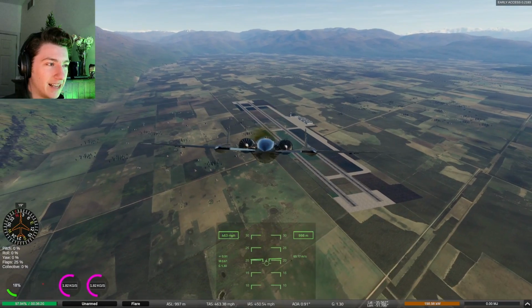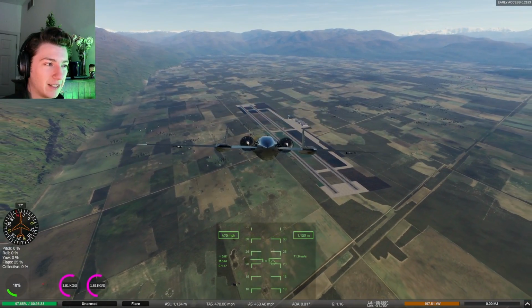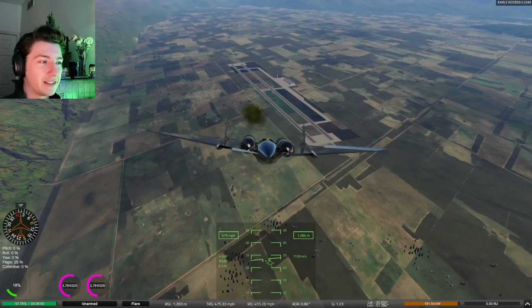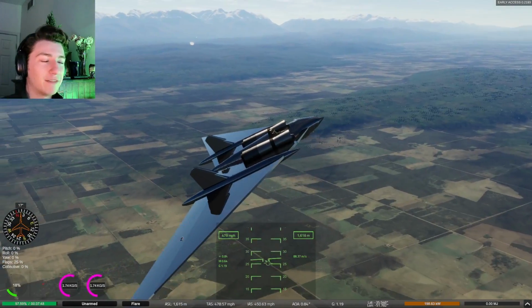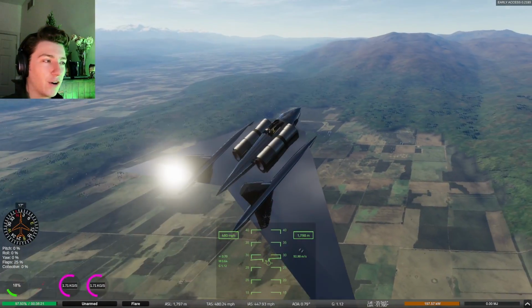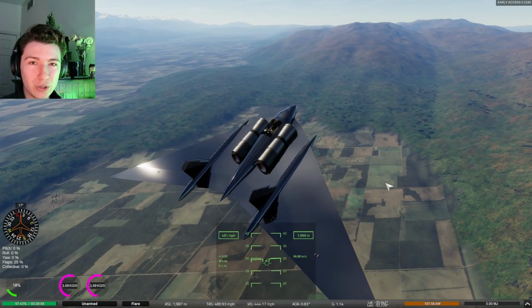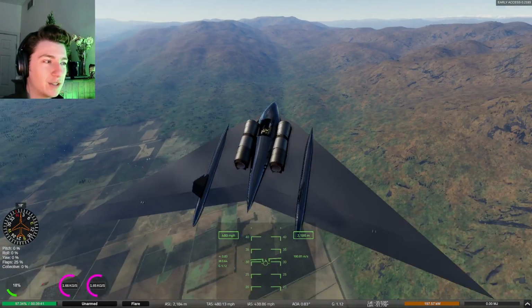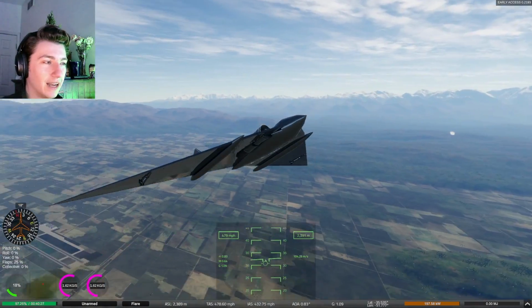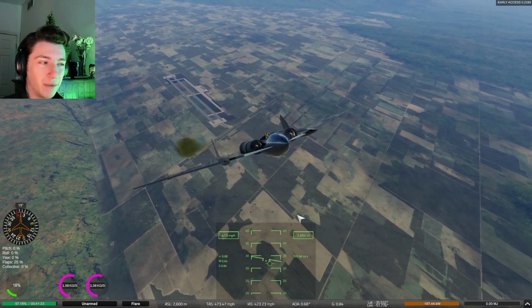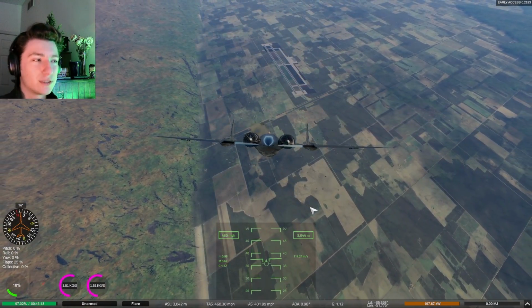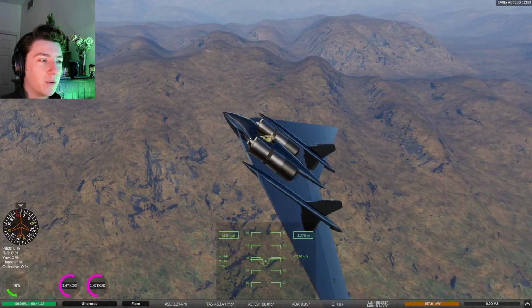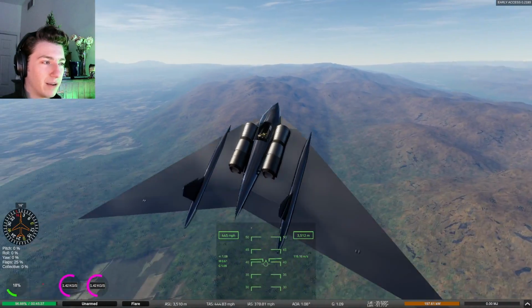You'll notice it has a bit of slip. There are things we can do to fix that, but at some point with fly-by-wire craft, you have to be mindful of, are you fixing a hardware issue with software? So like, would it be easier? I could fix the slip in the fly-by-wire system, or I could fix it by adding bigger vertical stabilizers. You got to think about what's a real solution to my problem.